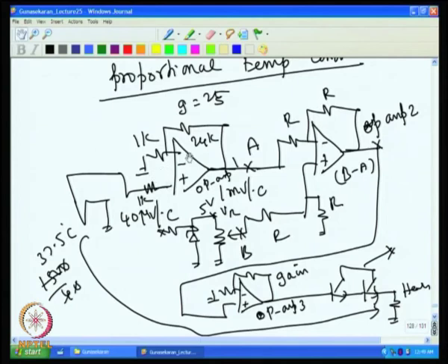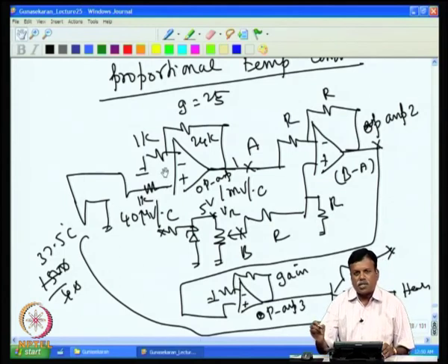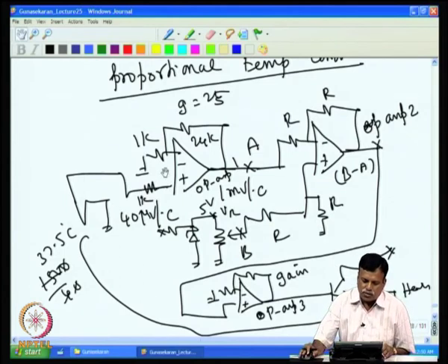Of course, in this case input impedance is not a serious problem, because the thermocouple has very low internal resistance. So, input impedance error is not much. In this case, if we consider only offset voltage drift and the bias current drift itself, it is enough. More importantly, when handling such a low level signal, it is the offset voltage drift that is to be considered very often.